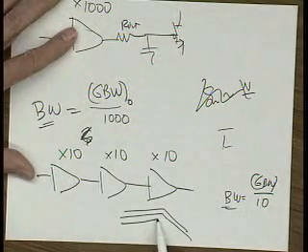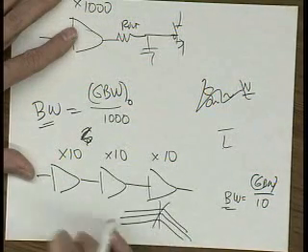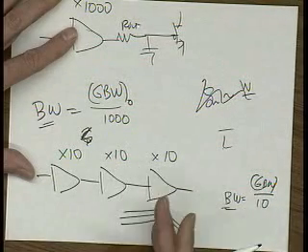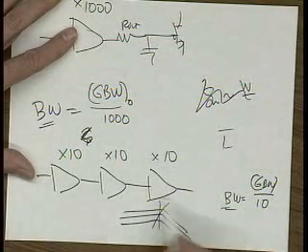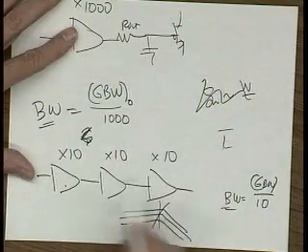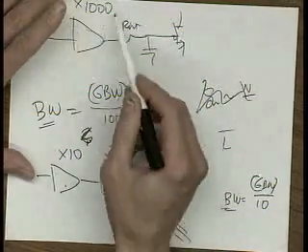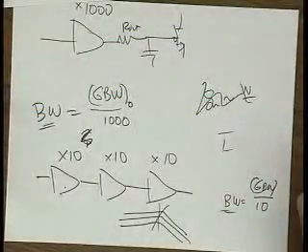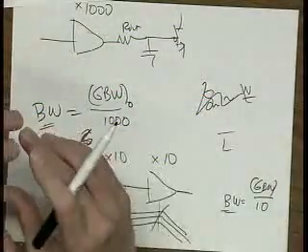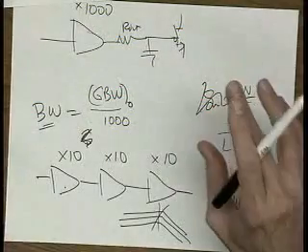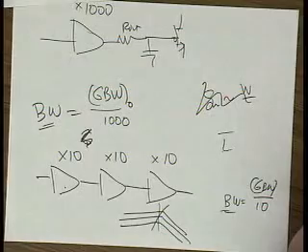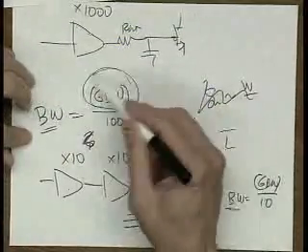And that will, of course, degrade the bandwidth a bit by putting a whole bunch of stages of approximately the same bandwidth. It won't be quite the same as the bandwidth of one stage, but in actual fact, it'll still be a lot more than this. So the fundamental thing to high frequency design is more stages of lower gain. That's how you get faster circuits to work, right? And it all comes from this gain bandwidth product thing.